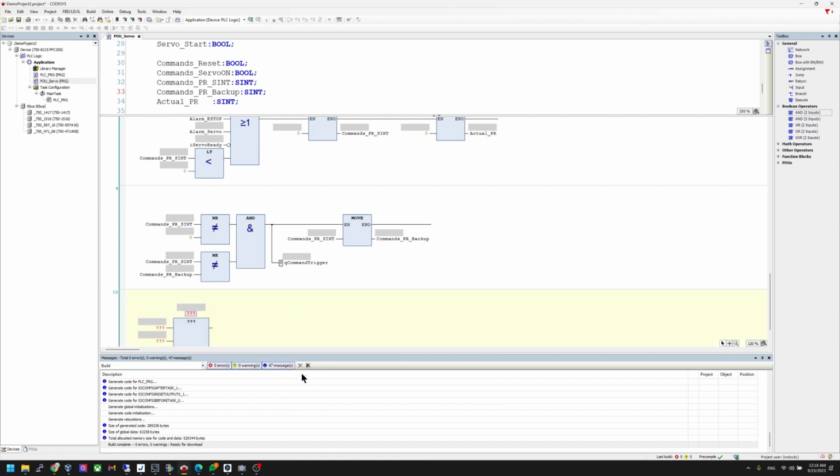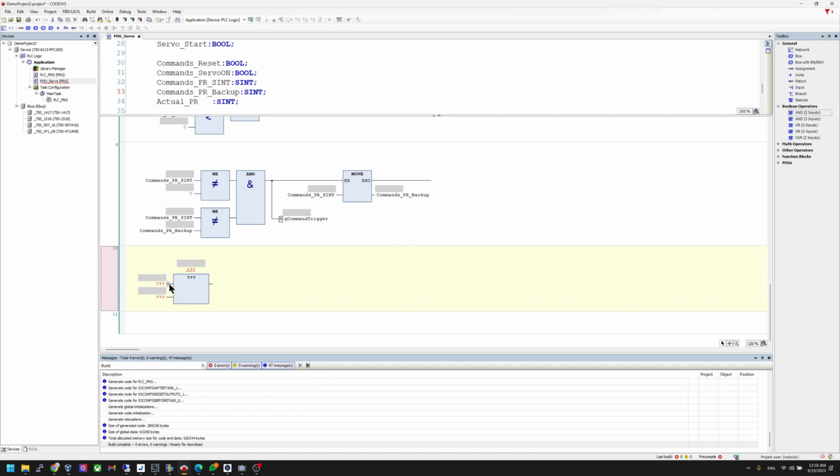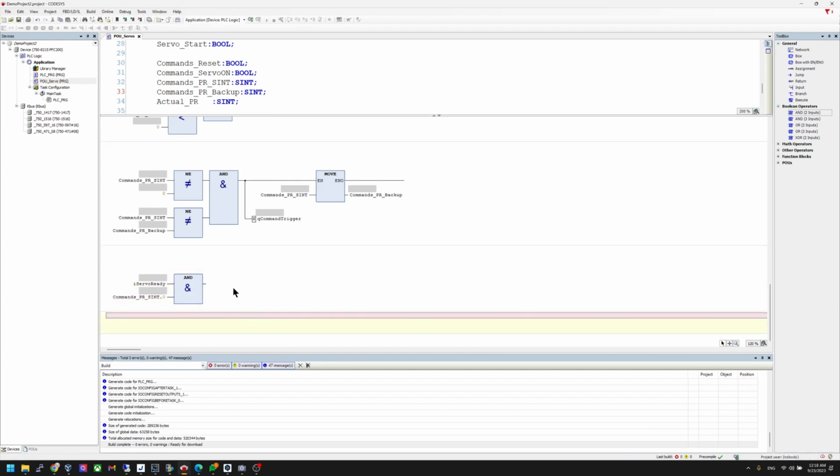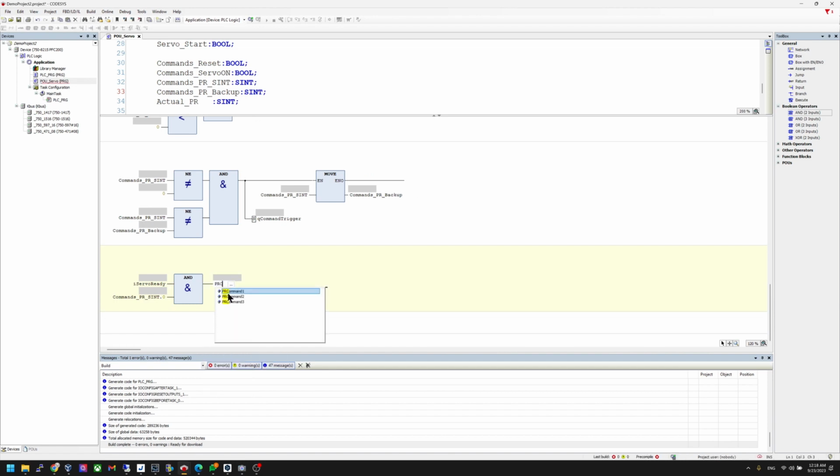If the servo is ready, so it means the servo is ready to run, and the input and the control voltage is also okay, and the servo motor power supply is also okay, and this servo ISO ready will become true. And then you need to put AND logic in here. So AND what? And your command signal dot bit 0. And then for the result, you can put the assignment here, PL command 1.